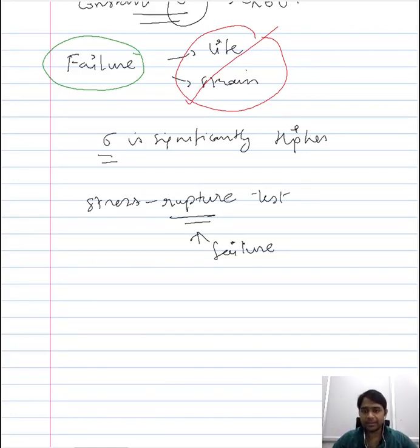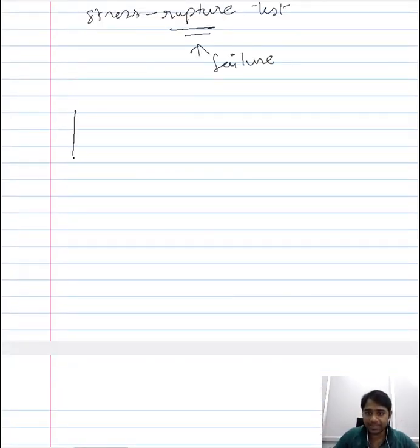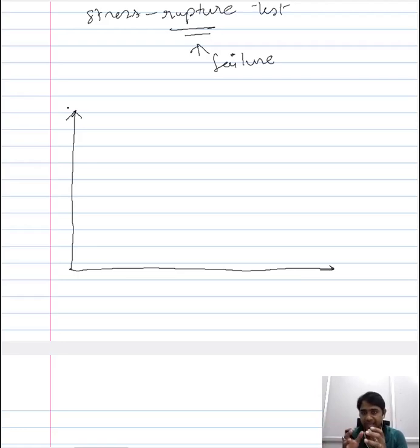Now when you compare the behavior of material during creep testing to that during the stress-rupture test, it is largely noticeable even in the simple representative curve that you would get from these two tests. This is just a schematic representation. Both tests are carried out in a similar framework, meaning you have a constant temperature and a constant stress, a constant mechanical condition, and the temperature in both cases is higher than ambient. However, the stress is of a significantly higher range in the stress-rupture test compared to the creep test, and whatever change in behavior you observe in the material is primarily because of this stress.